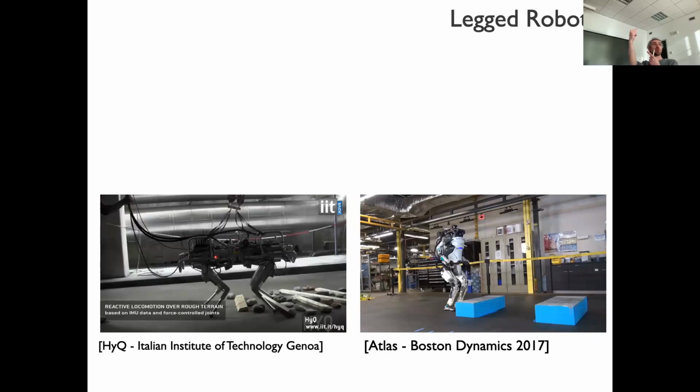So you don't need to multiply it by a lot to have the torque that you desire at the joint. And having smaller gear ratios, you have much less friction. And less friction means it's easier to control the system. So it's mainly on the hardware aspect.